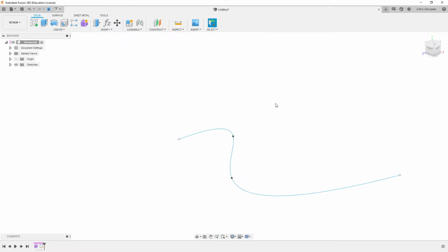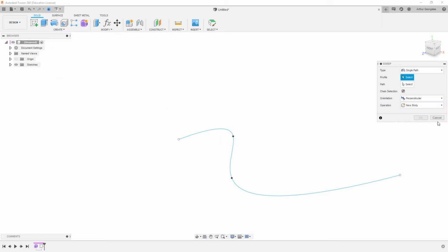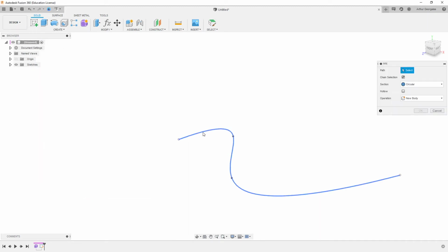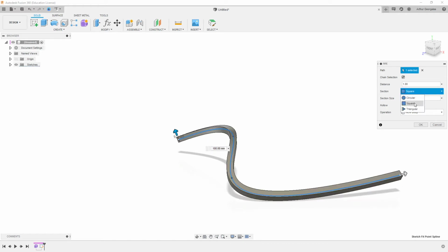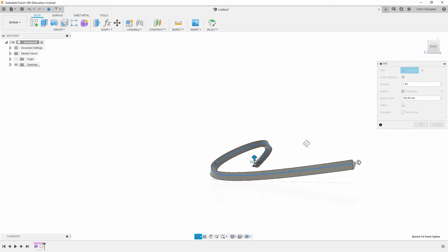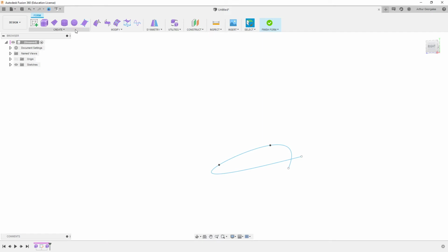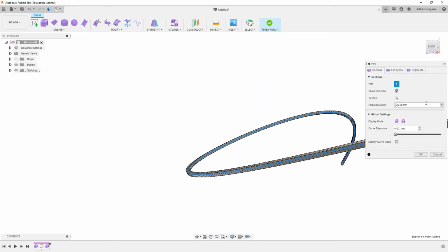And what that'll do is allow us to create a pipe similar to a sweep, right? So in Fusion, we've got sweep, and solid modeling actually has its own pipe command. It's just a sweep with a circular, square, or triangular profile, which is super good. But in freeform modeling, we can create a pipe across here, and what you'll see is, if I change that diameter up to about 40,